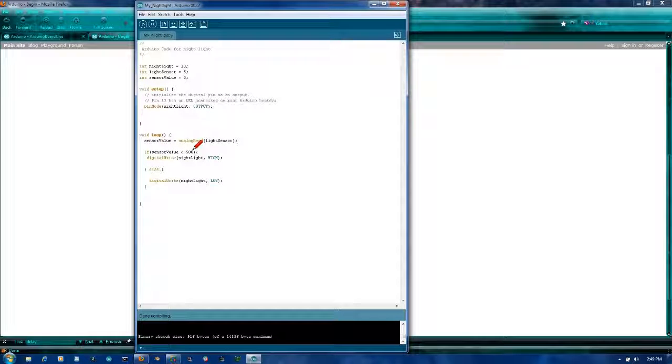Okay, and we open up the serial port, and then we put in the speed. By default, your serial monitor should be configured to 9600. You'll see different speeds for different devices. I think I had to kick it down to 4800 for the GPS. There's 2400, and you'll see 115,200. So it can get a lot faster, but for our needs, 9600 is perfectly fine.